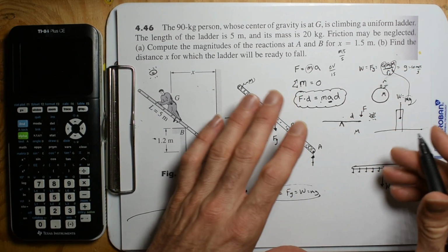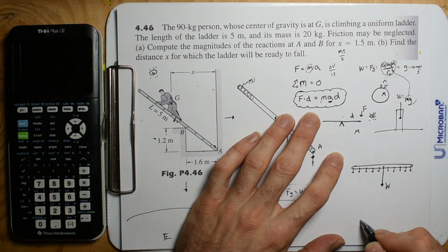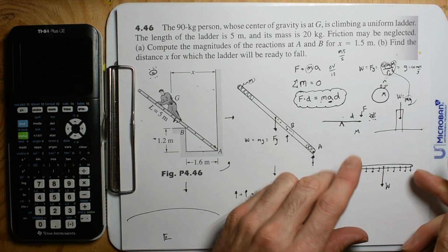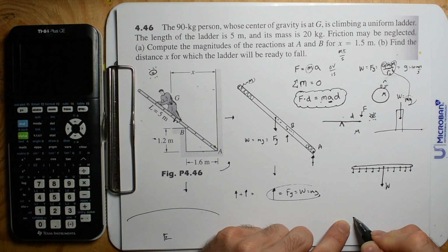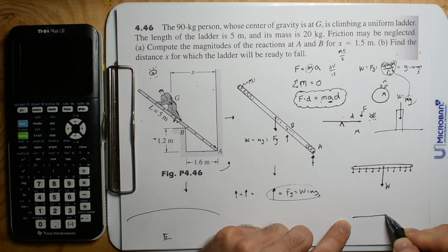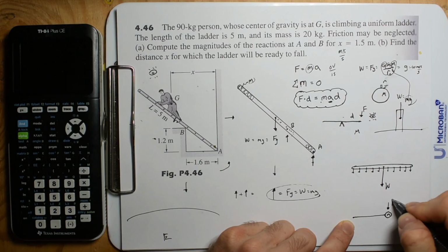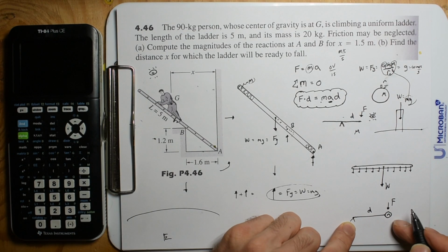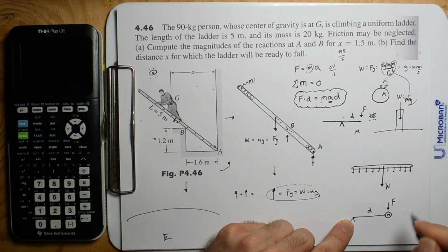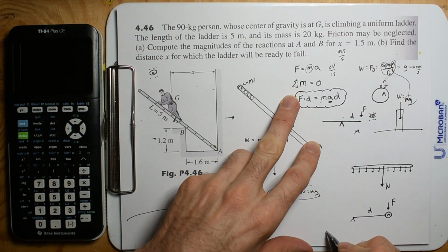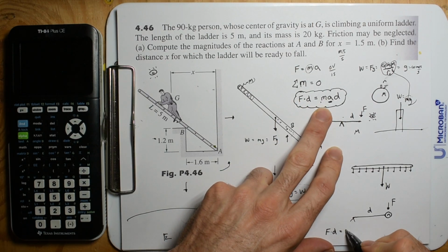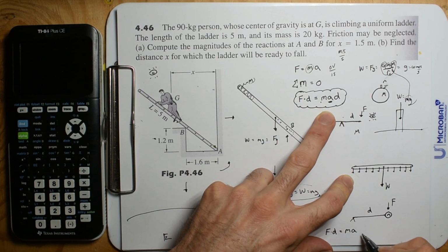But I can do it. I was just like, well, let's not take a moment. So we're going to make this ladder even simpler and just say it's a pivot with a string or a massless rod, and then a mass out here, and then a force right here. So here's our teeter-totter or our pivot, here's our distance. We do generate a moment, so the sum of the moments is F times d, and that's going to equal this mass, its acceleration.